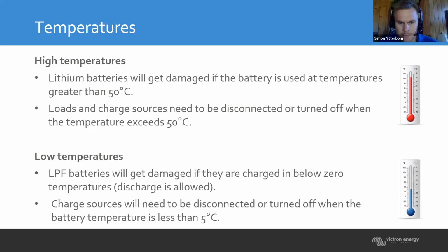The second thing that is critical for lithium batteries is low temperature. A lithium battery cannot be charged below freezing. Inside the battery, there's an anode and a cathode, and there's separators in between. It's sort of a fence that the electrons need to travel through. And if we're charging this in a really cold temperature, we could potentially damage the separator and parts of the battery because they're not designed to do so.